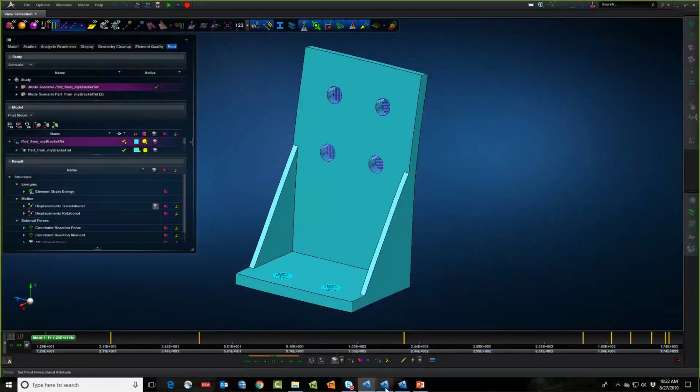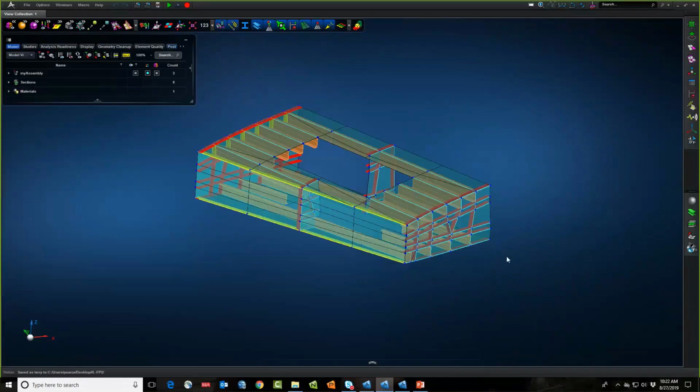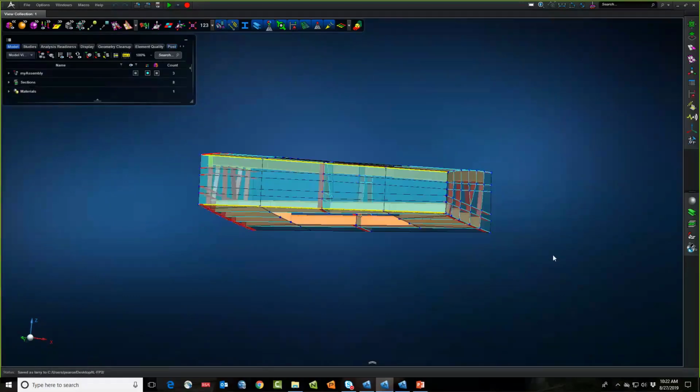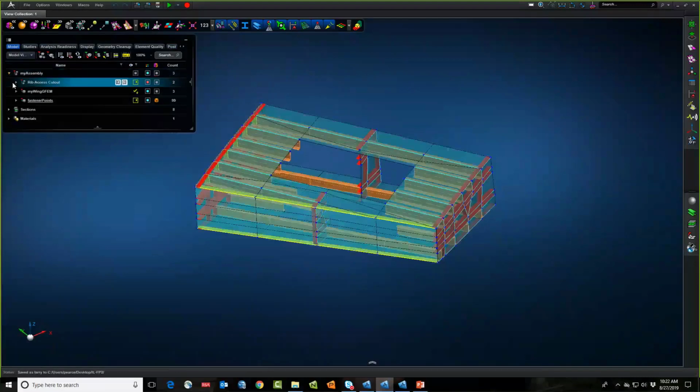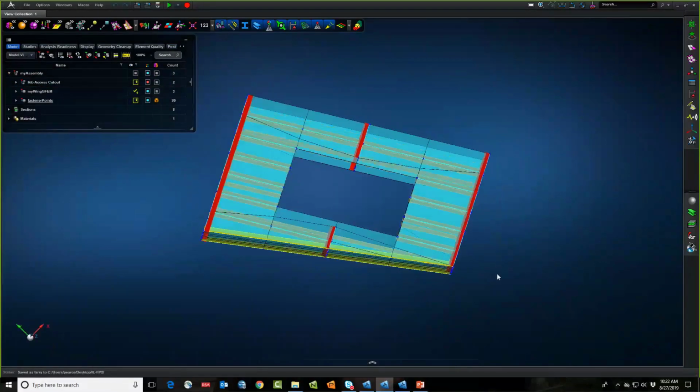All right. Let's look at another example of using an orphan mesh to create something that we can redesign and repurpose. Here I've actually got a small section of an aircraft wing, and we'll let this represent the global finite element model, right? Just a global coarse grid representation of the wing. And you can see there's a piece that's missing, and that's a submodel or a local model that includes the rib in that section. And perhaps I've actually used that already on some analysis, and I want to import that into Apex, and I want to reuse that for a subsequent analysis.